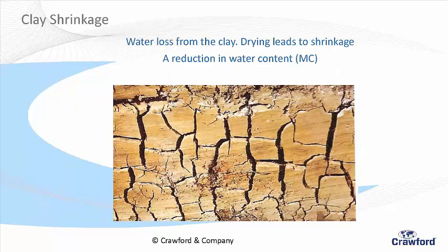Clay shrinkage. So this is, any questions? Fire them away, okay? I'd prefer that. So this is clay shrinkage. It's basically water taken from the clay, and the moisture content drops. And then you end up with what they call a desiccated clay. Have you heard that term before? Yeah? And you end up with a stiff, hard, fissured clay. And it's really, really hard.